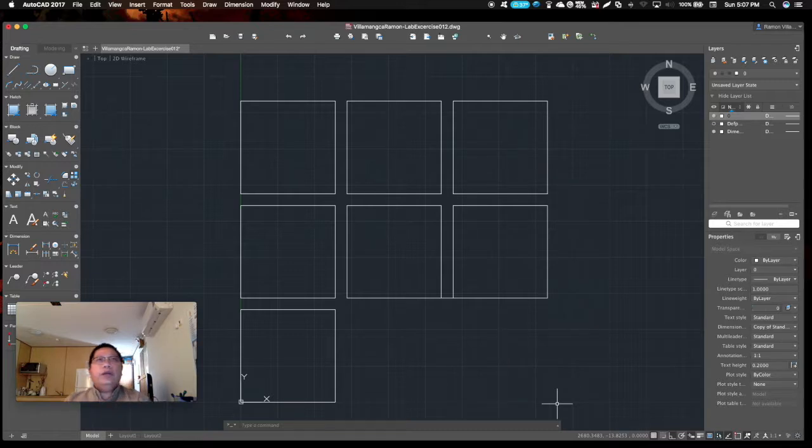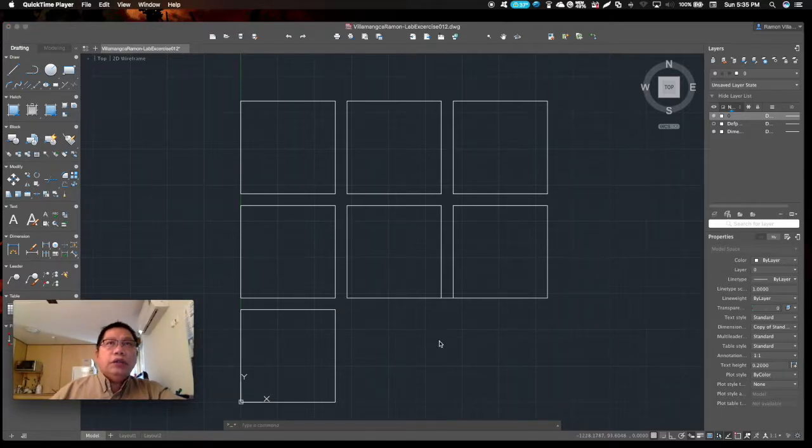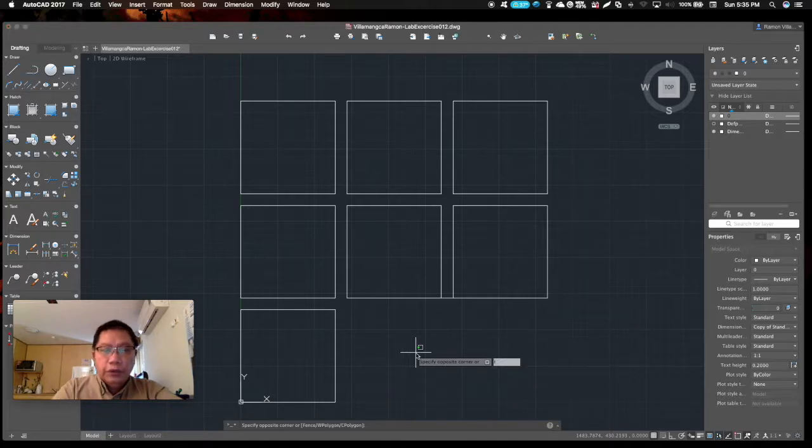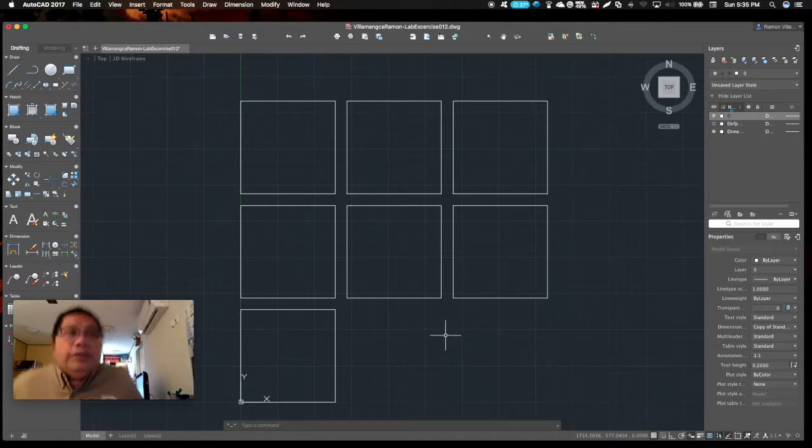Now we're through with the grid, so we're ready to start inserting our objects. But first, let's turn off ortho because it will not help me, but actually annoy. I think we still have one more to trim. Trim all this line. Okay, now we're ready to insert.